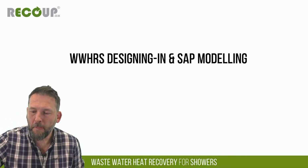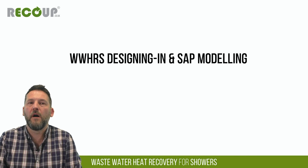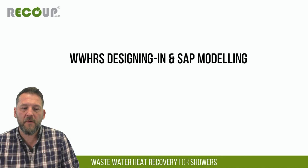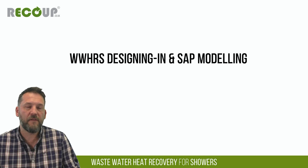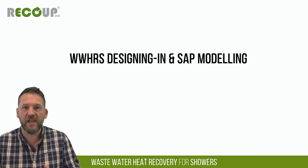Yeah, 2 or 3 questions. Maintenance on the drain systems, what's required? On the recess drains, essentially the wastewater heat recovery element is planned maintenance free, as all wastewater heat recovery is. However, if you are installing into high shower traffic environments and commercial environments, any wet room drain is going to need an element of planned cleaning within that.